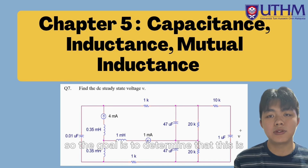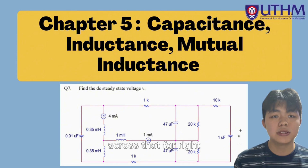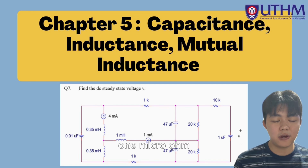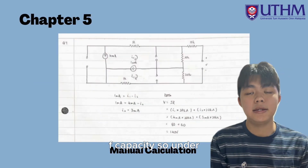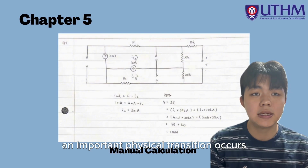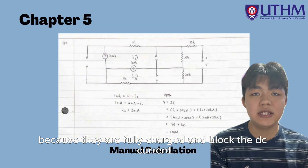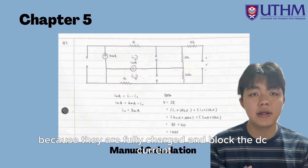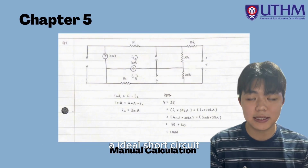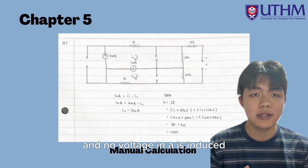So the goal is to determine the DC steady state voltage across that far right 1 microfarad capacitor. Under the DC steady state condition, an important physical transition occurs. All capacitors act as open circuits because they are fully charged and block the DC current, while all inductors act as ideal short circuits because the current is constant and no voltage is induced.